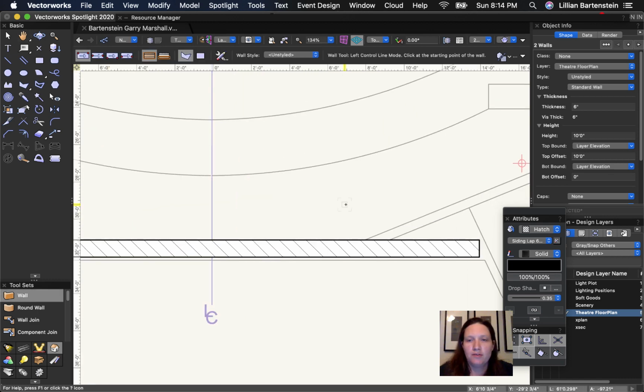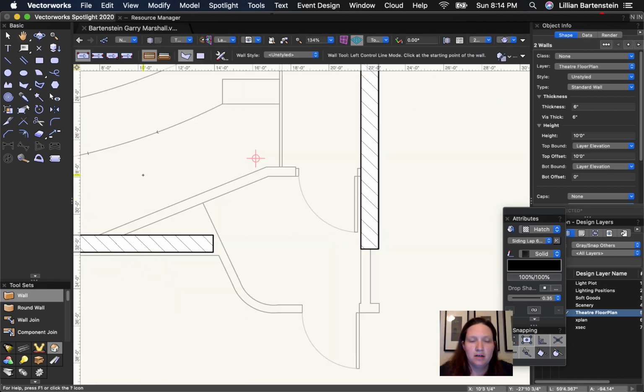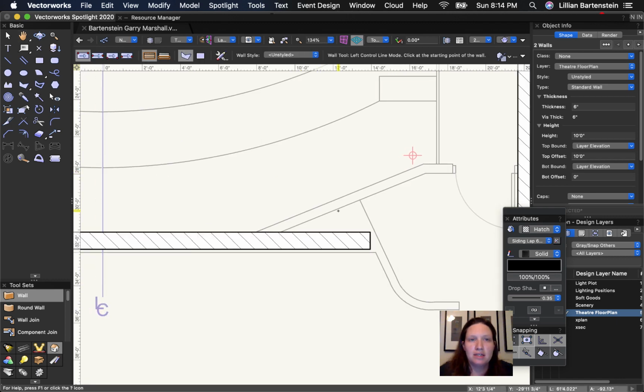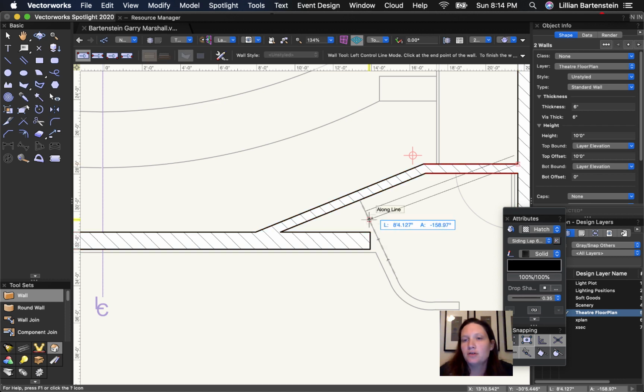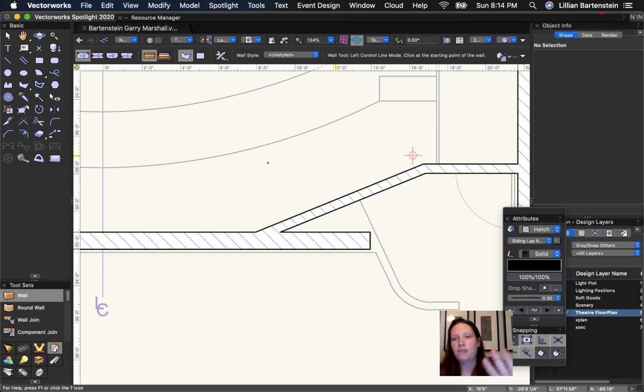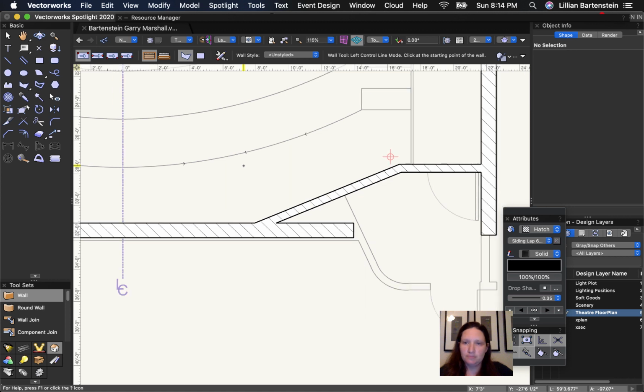All right, same thing over here, right? And it's gonna be even easier. So I'm still using this left line, this left control line. So I'm gonna find that endpoint of that line, come right to this endpoint, and then I'm gonna just hold shift so that I go horizontal until it locks in to that object. Great, now I can just back my way out by hitting delete.